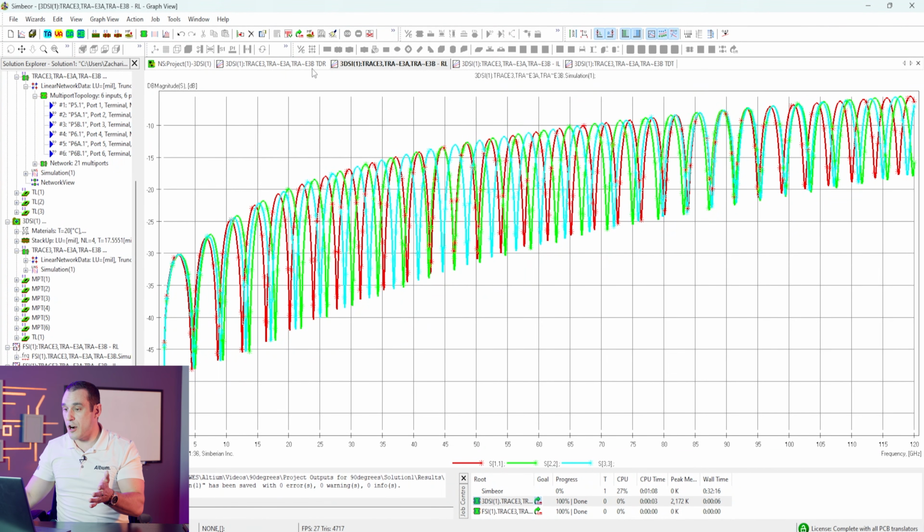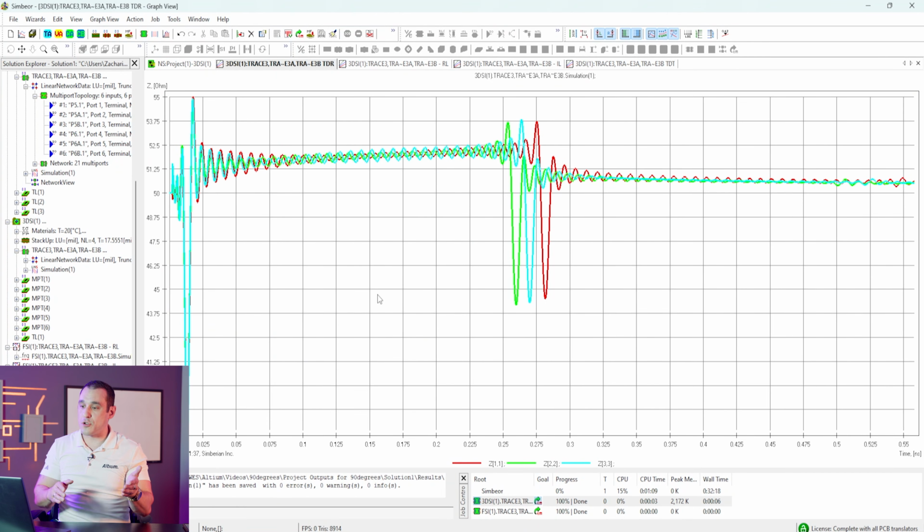And what about the TDR plot? The TDR plot also shows different timing, again, as we would expect, because these are time-based plots. We do see that the reflection here from the far end happens latest in the longest interconnect. That's exactly what we would expect. But we see here that the magnitude is essentially the same for all of these. I don't see any difference in the basic signal integrity metrics for any of these traces, whether we have a 90-degree bend, 45-degree bends, or curved bends.